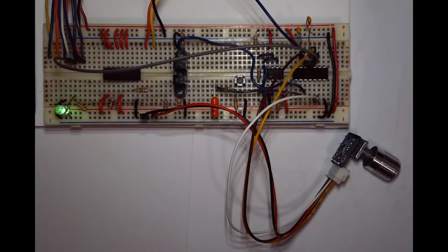All right, this is my circuit for lab number 5, and you can see here that I have the HC14 and two of my wires, the DT and the data, are going to some pins. Actually, it's wired a bit different than shown in the lab, but that's okay for the demonstration. And I also have a connection to ground and to +5 through the rotary encoder. And then the two outputs from the debouncing circuit are then fed to the inputs. This is D0 and this is D2 to act as the counting inputs.